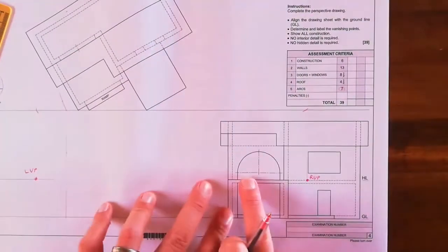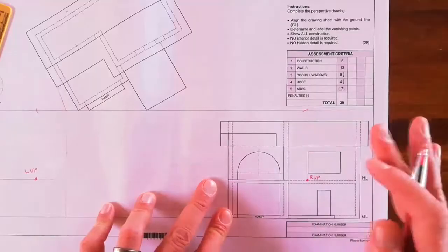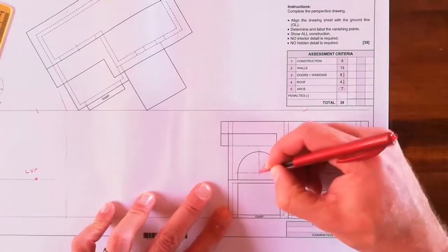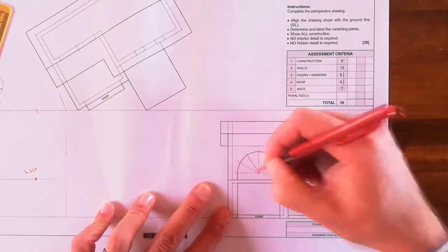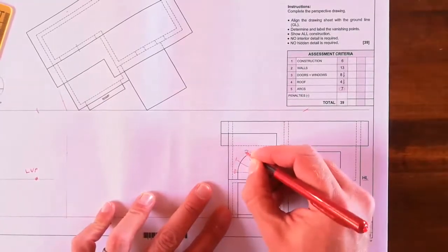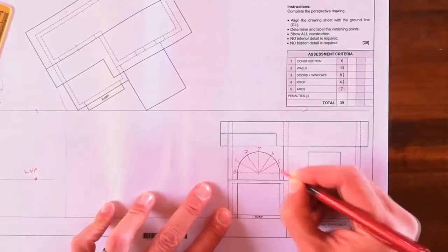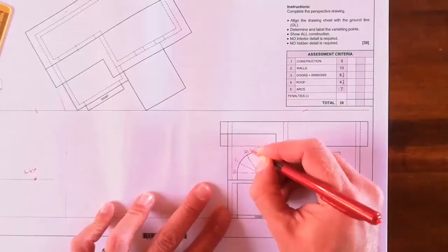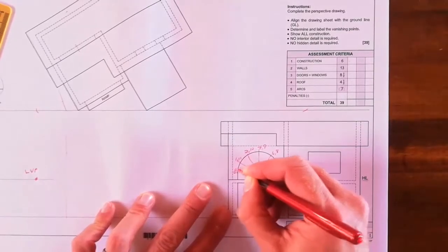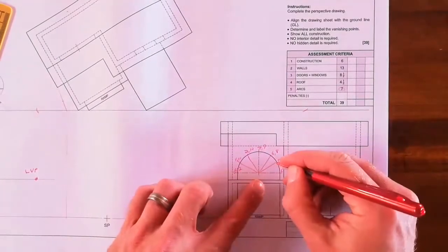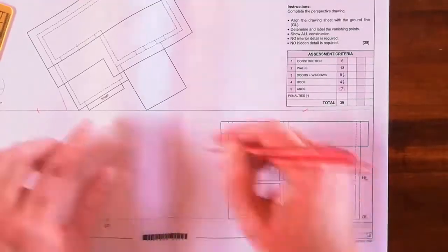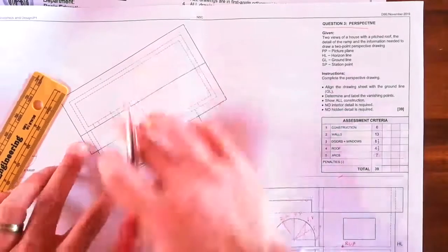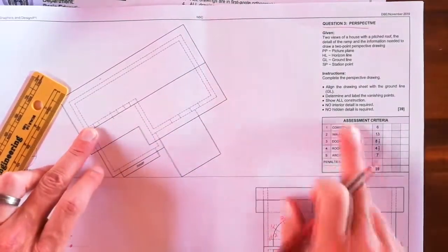Okay, so this arc here, if you have a circle, you're not sure what to do, you divide it into 12 equal parts using your 30-60 degree. Okay, that's already marks here, and you can number it. All right, you can number it. It shows that you're confident and you know what you're doing. Okay, and those lengths here you can also bring over to this here and bring your numbering across. That's already marks for the construction of this arc.